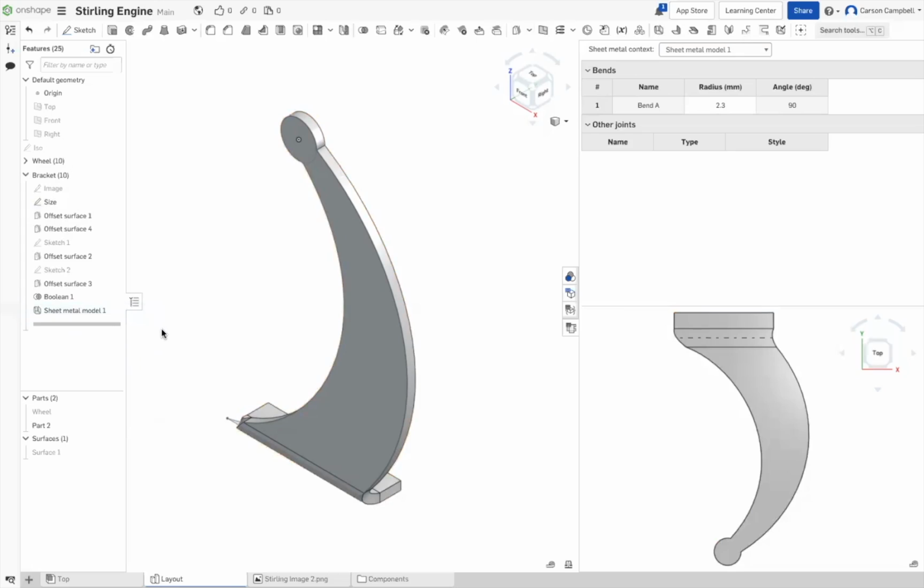Just in case you wanted to reverse that. For 5 years, I didn't delete them, and it became unruly. If I go back to a model that I did 5 years ago, I've got all these surfaces and I don't know why they're there; you can't manage them. Then you start grouping all your features together. The very last thing you do in that folder is you delete your references so that they don't accumulate and become unwieldy. You can Control Z and put that delete feature back up there.